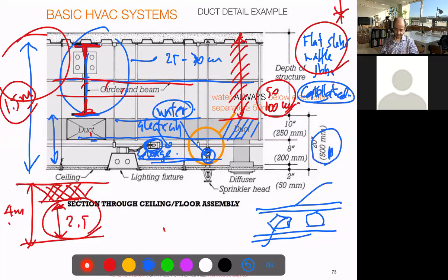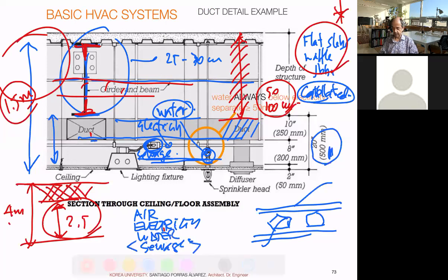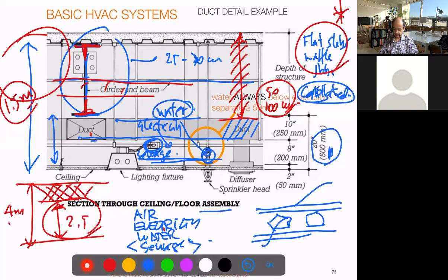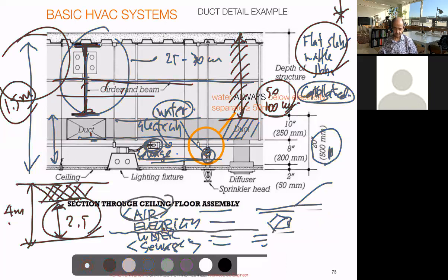So careful with this. So it's always air, electricity, water, and sewage if it is crossing somewhere by, right? So this is in the highest part, middle, lower. This is not so vital, only those two must be under, but since, as we said, air takes a lot of space, we put it first so we can always access and repair or service the lower elements.